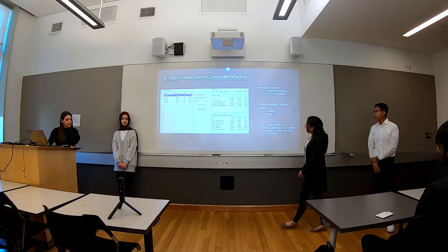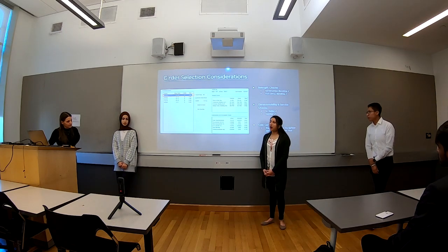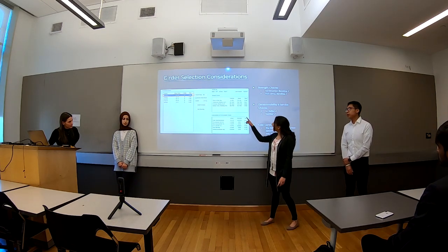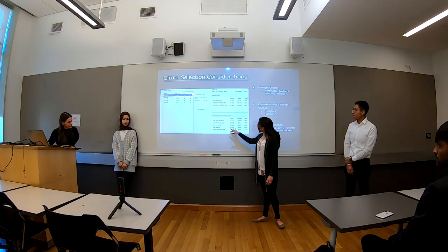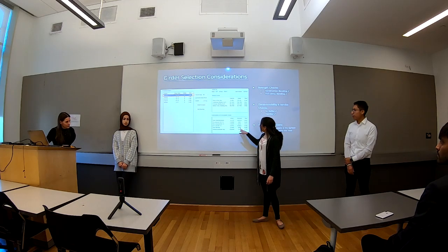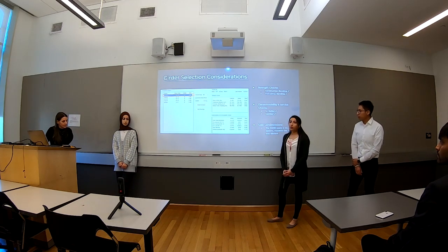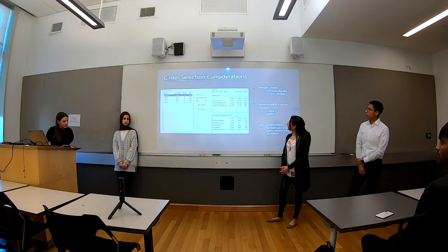As you can see, we ran with a composite action of 90% here, giving us a total deflection of 0.1243, where the allowable is 0.125, so it meets our requirements.